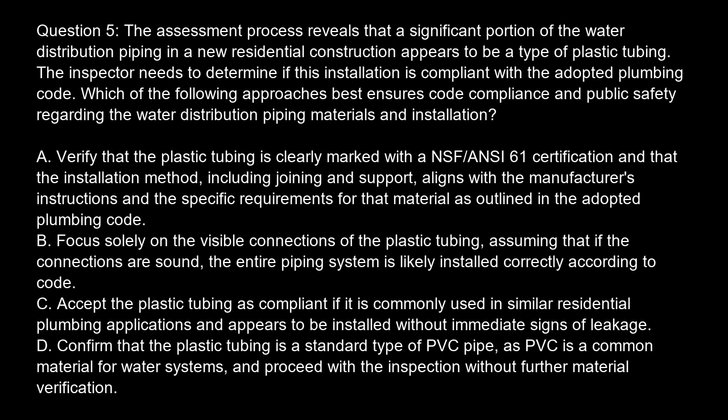Option A. Verify that the plastic tubing is clearly marked with a NSF/ANSI 61 certification and that the installation method, including joining and support, aligns with the manufacturer's instructions and the specific requirements for that material as outlined in the adopted plumbing code.